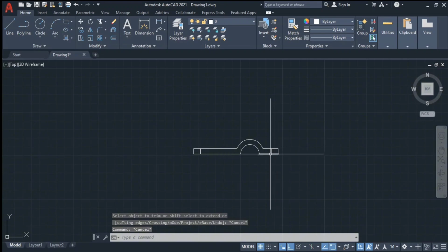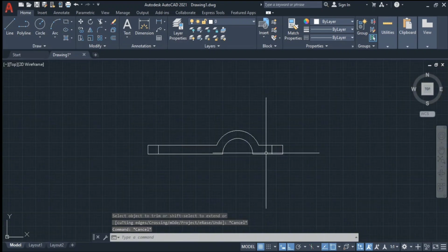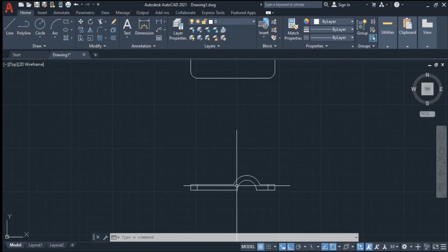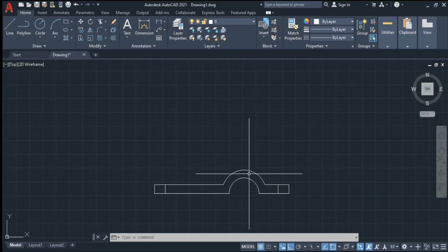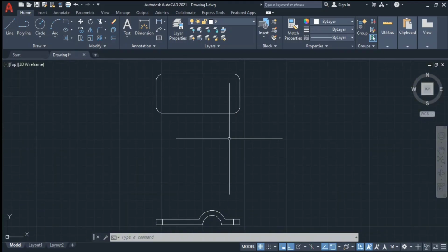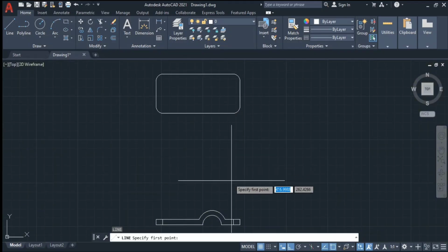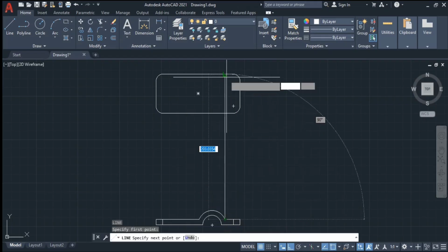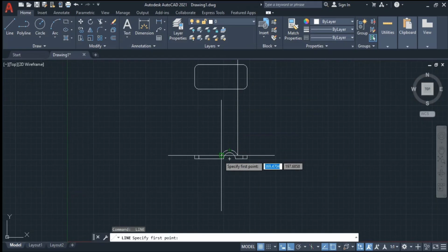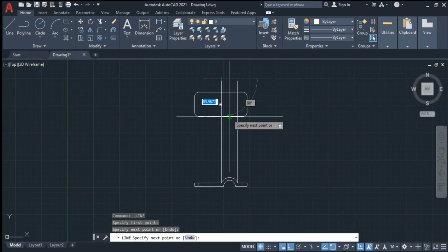That's it. So these are the fillet lines now. Okay, the second thing, since it is a circular cylindrical bosses here, so those will be projected here also, right? So in order to show them, L enter and specify first point and move like this. Do the same thing here also.